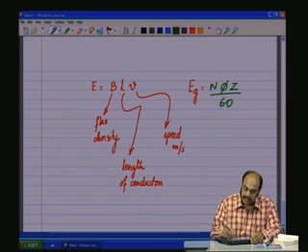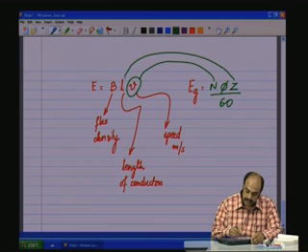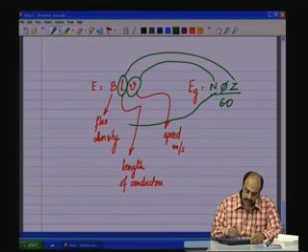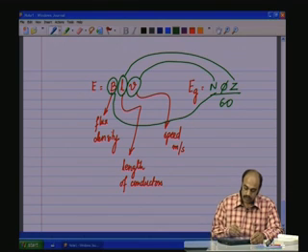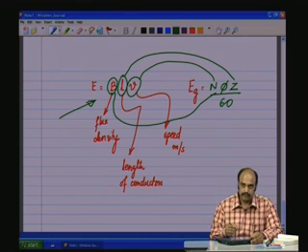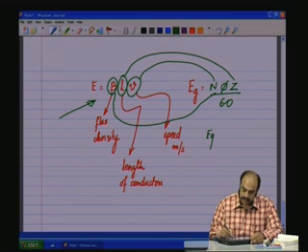Now, N is the rotation, revolutions per minute, rotation of the rotor. So, speed of rotation of the conductors. So, this is related to the V, velocity there. The number of conductors is related to the length of the conductors and the number of turns in the coil, and then the flux of course is related to the B. So, starting from this equation E is equal to BLV, the Faraday's equation or from the law of electromagnetics, one can derive this equation.